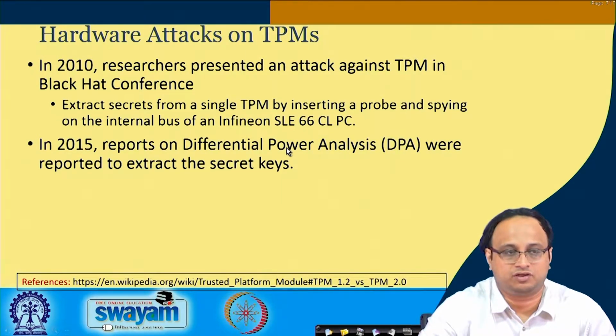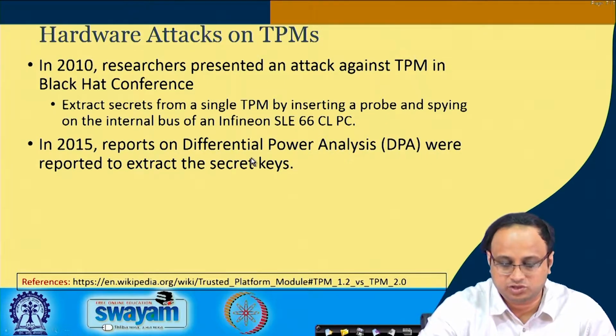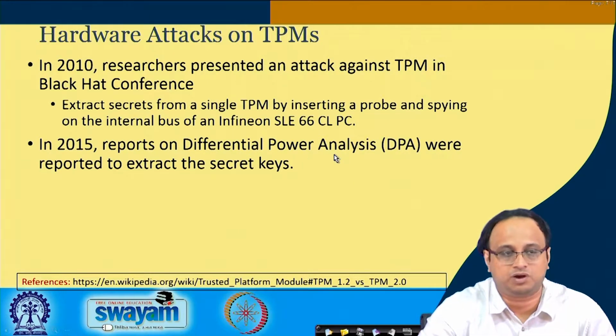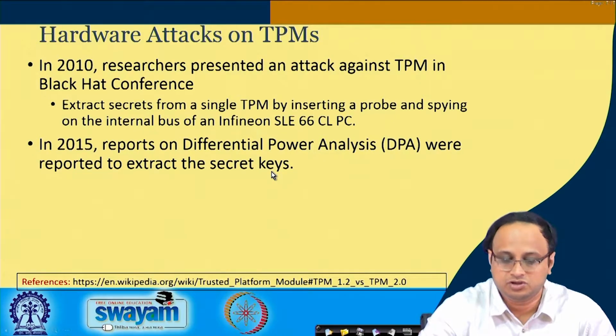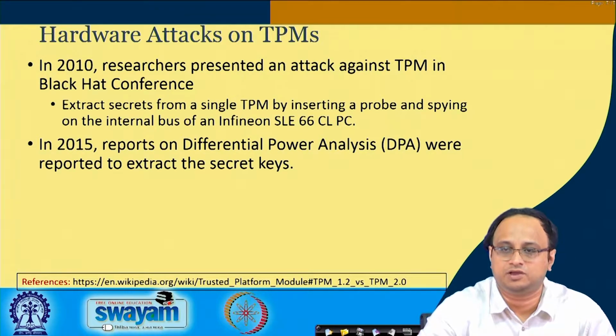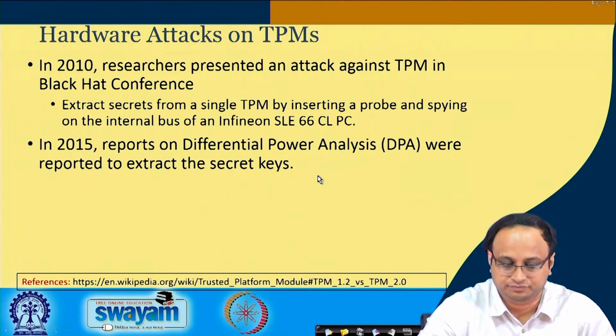This is a side channel attack, and we will be studying what differential power analysis is and how it works. The idea is that a DPA was mounted to extract the secret keys. So this shows that even if you have a nice architecture like TPM, storing secrets is not a very safe and secure means, because there can be potential attacks. At the same time, it tells us that we should build our crypto systems and crypto hardware with these kinds of physical attacks and side channel attacks in mind.